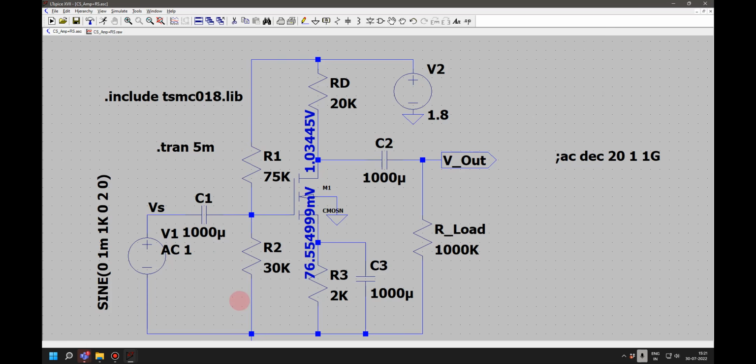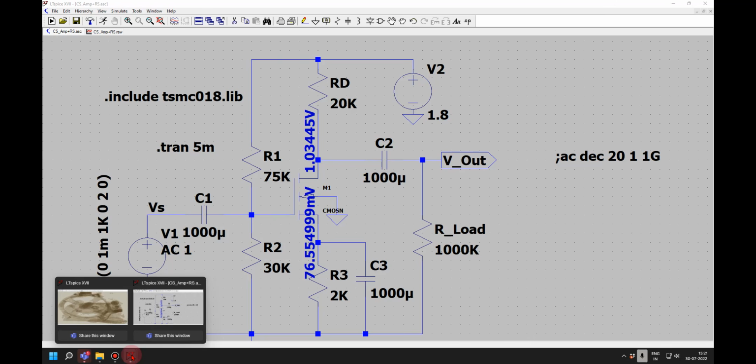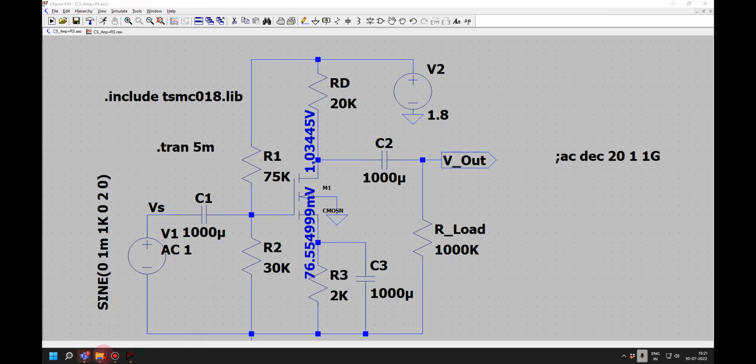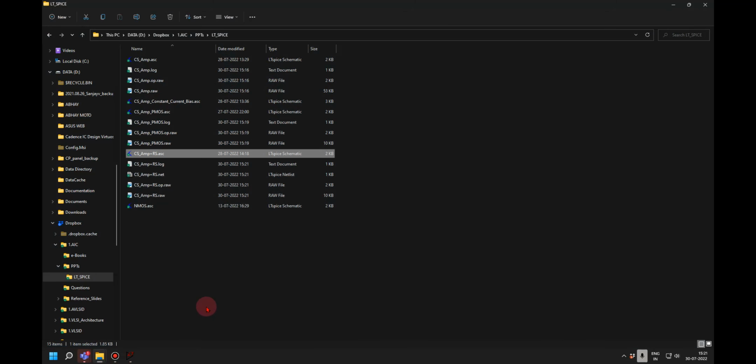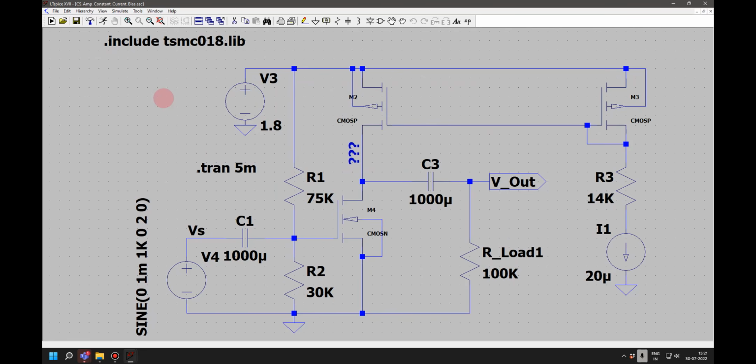Yeah, sir. Which one is recommended, the NMOS one or the PMOS one? As we know, both PMOS and NMOS have the same driving strength at the lower node. So will it make any difference between PMOS and NMOS? Doesn't make much of a difference, right? On the higher technology, like 180 and all, to get a proper inverter, you used to have a 2:1 or 3:1 ratio between N and PMOS. In that case, NMOS will be a better choice over the PMOS, right? You're talking about digital design or analog?